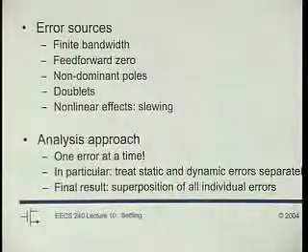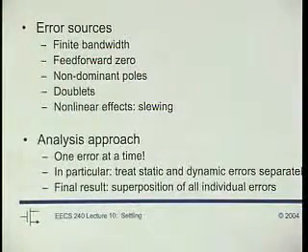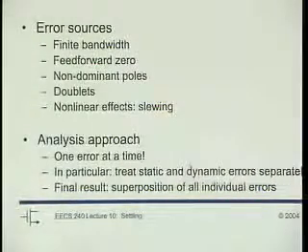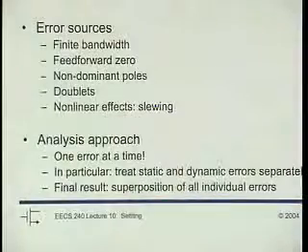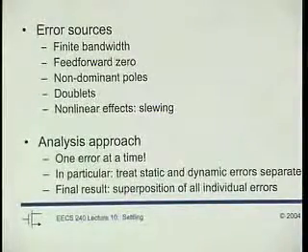So the finite bandwidth of an operational amplifier, of course, comes into play. The feed-forward zeros, the thing that we talked about, right? The feedback network also starts contributing a signal at the output. Well, that also can affect settling.